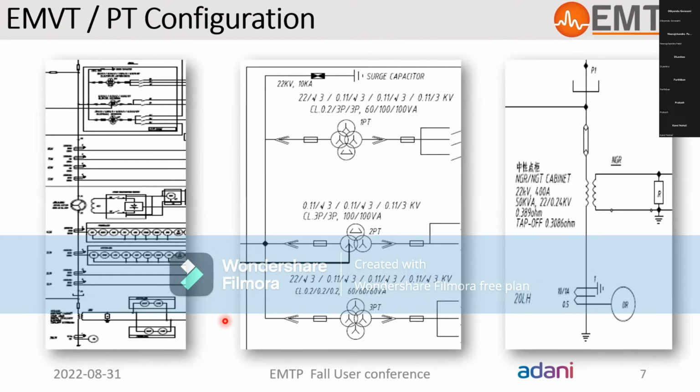So mainly this is the VT configuration. Here we can see the generator is connected with the system with the NGR. So it is a highly resistive grounded system, obviously for its application. And these are the 3 kinds of PT which we are using in this power plant. This is the one PT which has the open delta core.